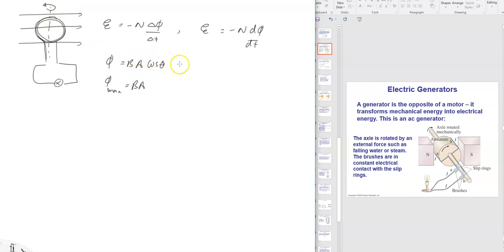So the things we know so far: the faster it rotates, the more electricity. The stronger the magnetic field, the more electricity. More flux, meaning the magnetic field and the area together, means more electricity. And then depending on what kind of resistance this circuit has, we can figure out what the current flow in the circuit is. Okay? Alright.